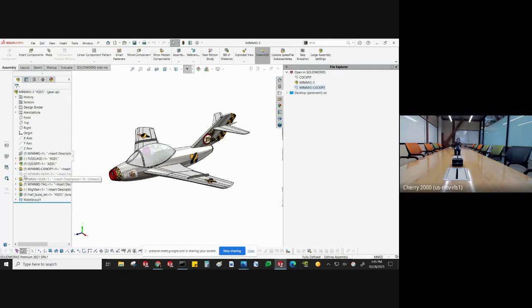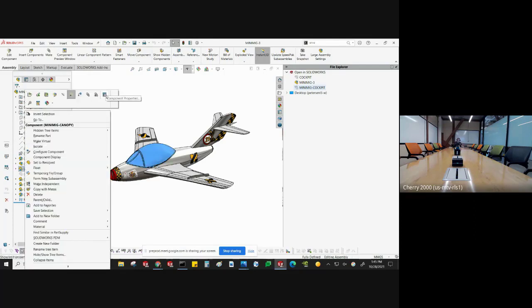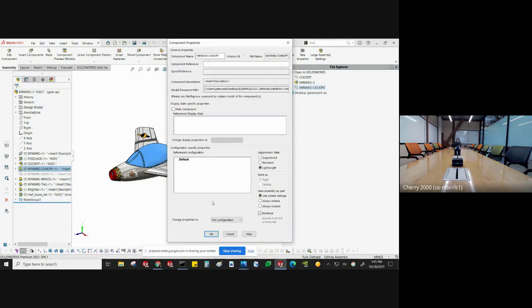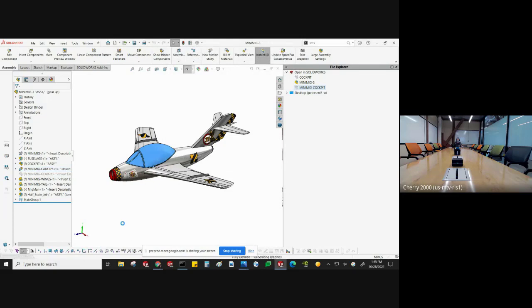That's the difference between telling whether it's full weight or envelope. But it's been around for a while. It's just really tough to get to because you right click and then you go look for a checkbox in this giant list. It's not the easiest thing to find. So if you didn't know about envelopes, don't beat yourself up about it.